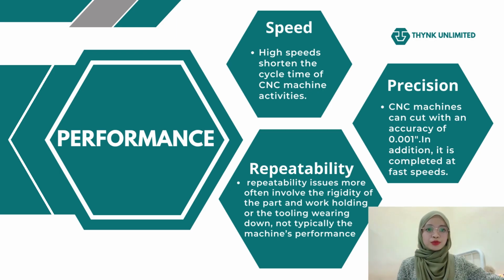Running from a computer program that controls the machine process with consistency and precision, a CNC machine reliably repeats all steps. As far as day-to-day operation, repeatability issues more often involve the rigidity of the part and work holding or tooling wear, not typically the machine's performance.